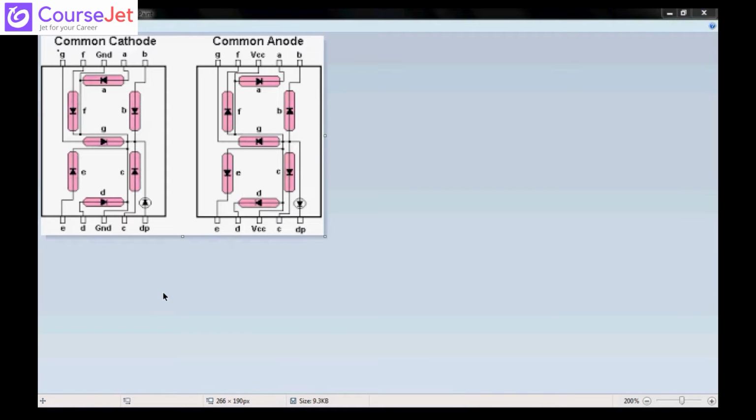All the LEDs are connected through a common ground. Like we did for LEDs when we connected them to port 3, we were giving only one ground and all the LEDs were connected to particular port pins. If we connect 8 LEDs also, we need not connect 8 grounds. One ground in common is enough.